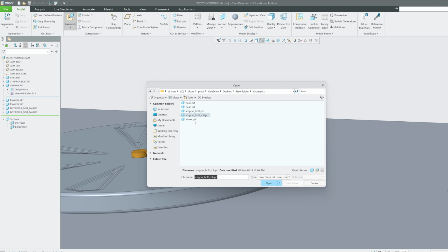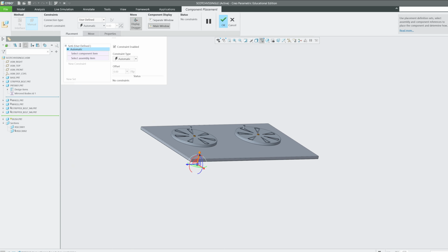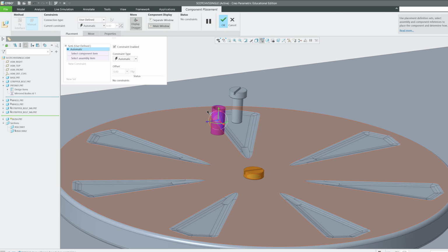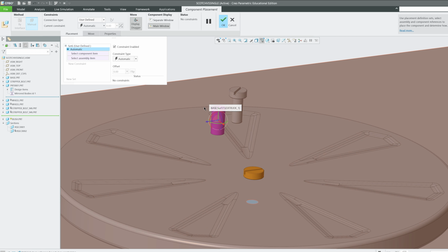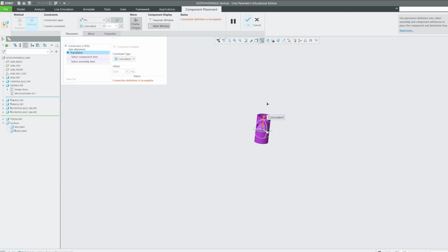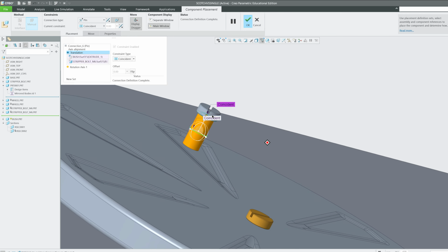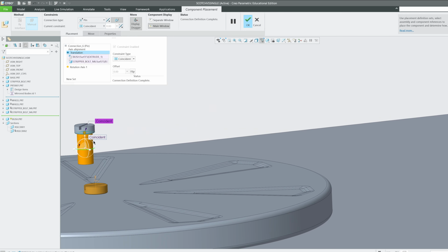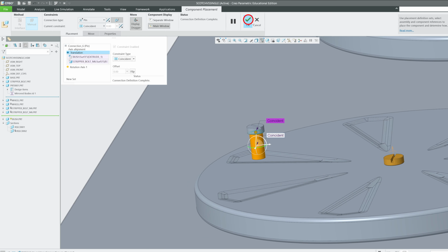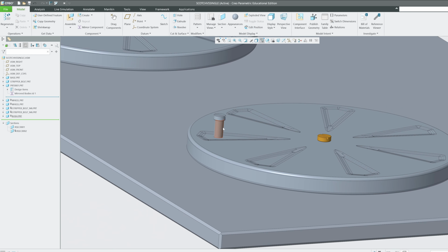Time now came to assemble this bush, and here we go. All right, so this bush can be a pin joint. Of course it needs to be pin joint. Yeah, so let's go here and make it pin joint. So axis to axis, and then of course flat to flat. Although the movement, I would say, is almost cannot be seen easily, but still let's do that.